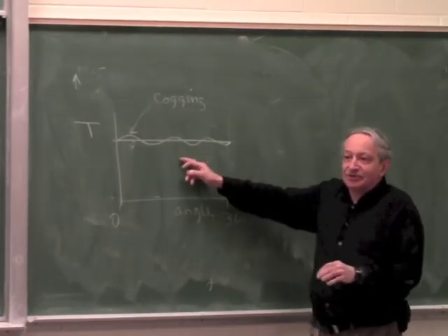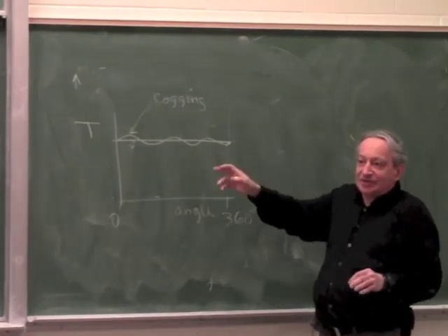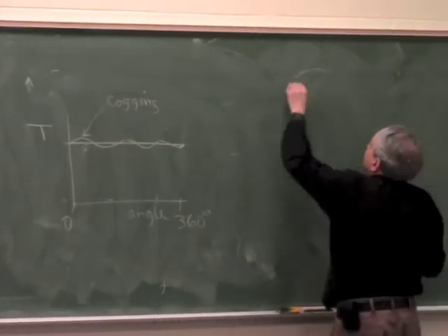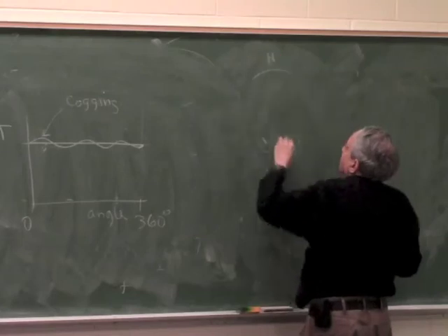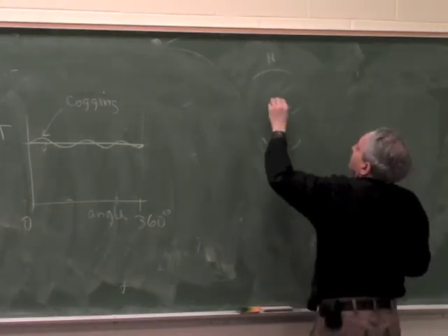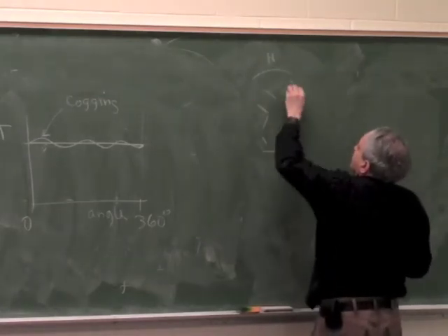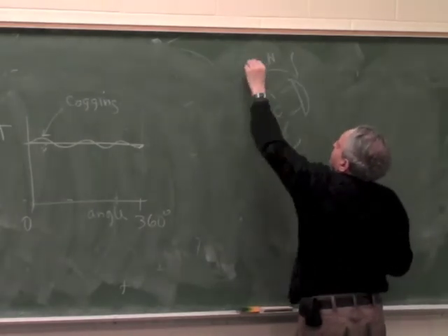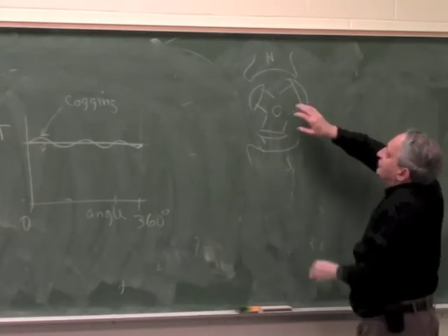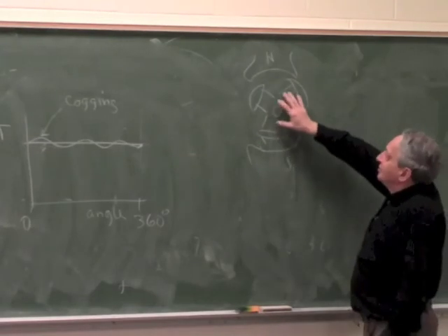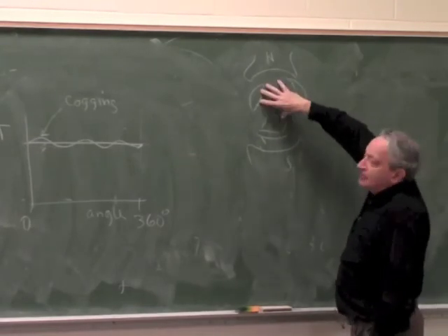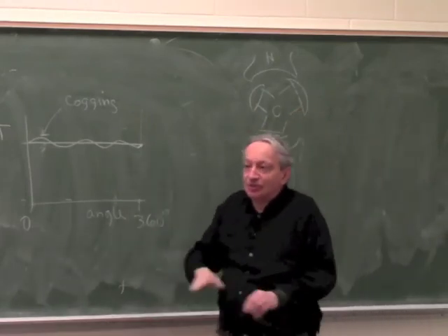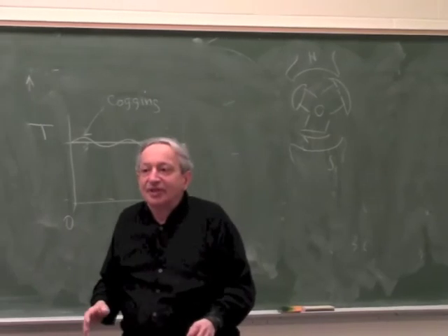In DC motors, it's the same, because the air gap changes. If you have a PMDC motor with N and S poles, and you have an armature like this with 3 slots, you also have variations in the flux, because the flux is a bit different as the armature is rotated a bit, okay? So there are also flux changes, so this problem appears in all motors. So why do we care, actually?